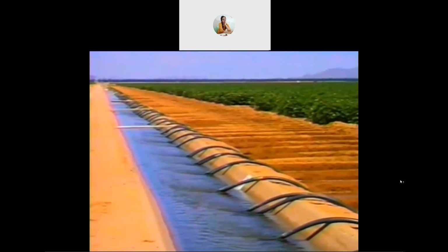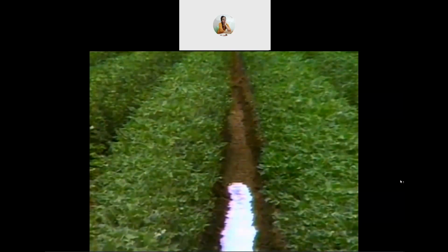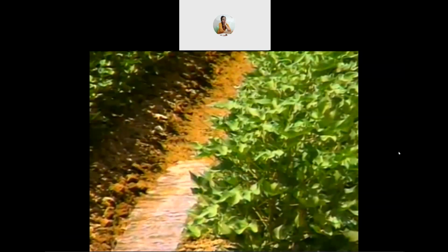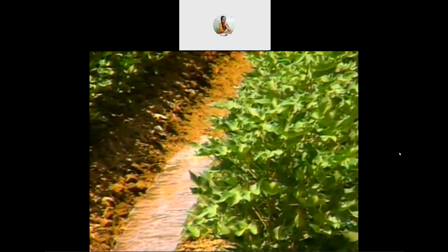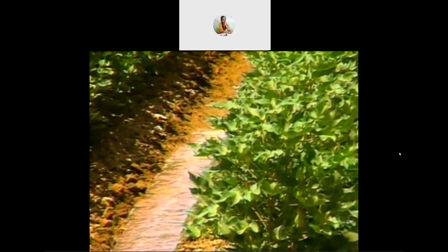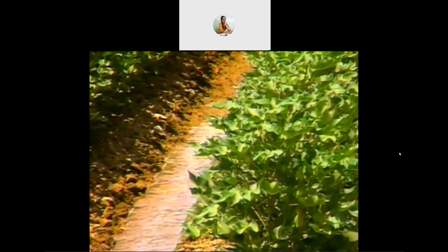Now you turn the water off at the head end of the field, and the remaining water seeps into the ground or runs off the field. The amount of time you left the water running is the set time. Notice that the head end of the field has a lot of deep percolation, where the tail end doesn't. This is because the opportunity time at the head end is longer than the opportunity time at the tail end.